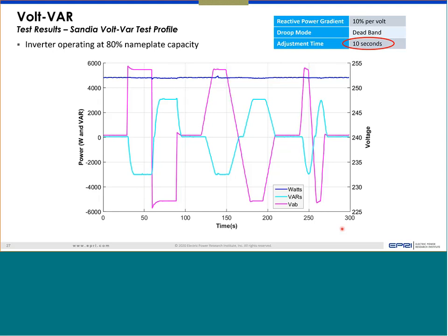What is the typical industry adjustment time for transmission level PV inverters? Honestly, I don't know the answer, and I also don't know if there's any typical number. Transmission level is especially more difficult because you have so many other things regulating the voltage. Do you really want the plant to do the control, or do you want the plant to be the slow response through a plant controller, as a kind of your auxiliary or backup, where you have other resources to regulate the voltage?